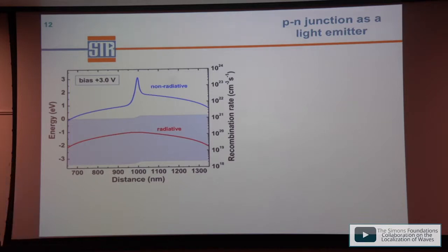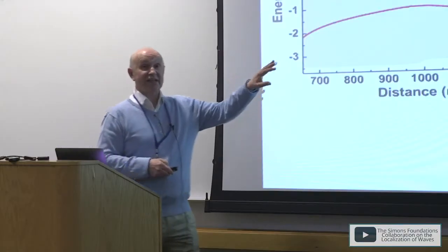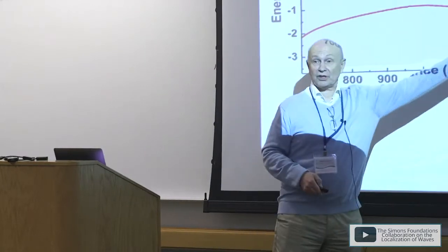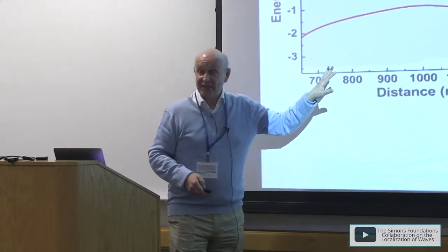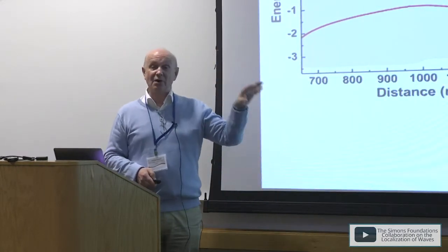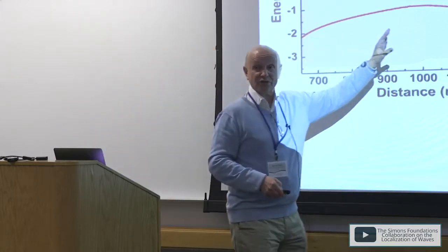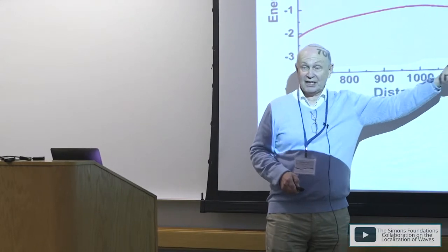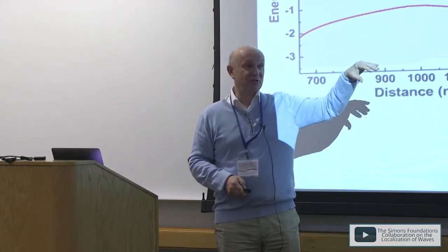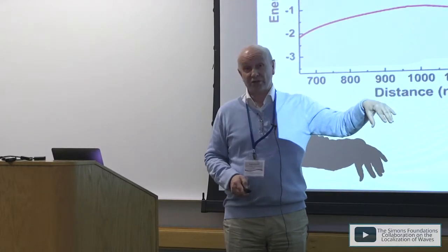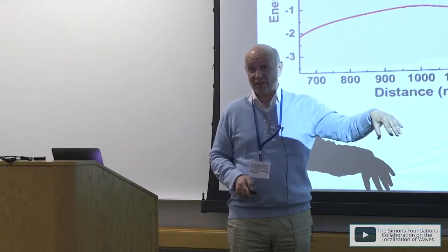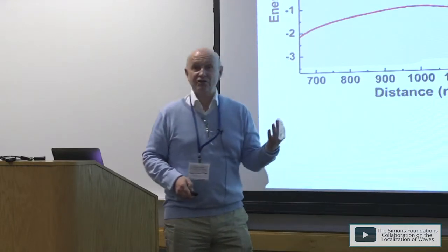What are the reasons? One of the reasons, as you see from this simulation, is that the recombination profile points out that electrons and holes are distributed over the whole structure. This means that a part of the electrons pass through the whole structure without recombination. They come to the ohmic electrode and are lost for recombination altogether. This process is called leakage.